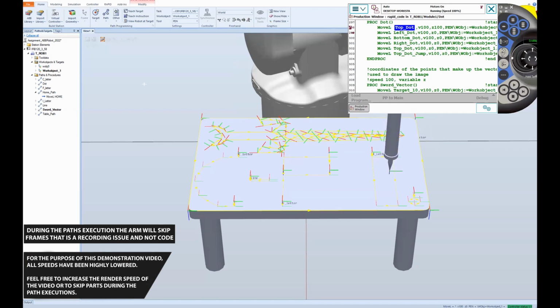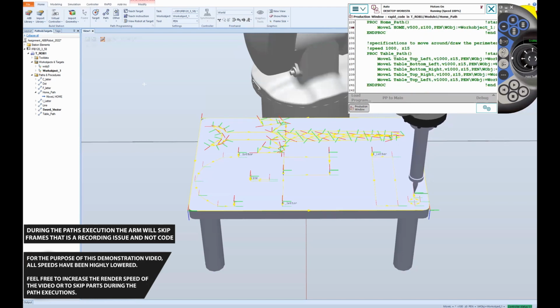So as an example, if the user is at 5 meters away from the system, the speed can be reduced to 80%. If at 3 meters, the speed can be reduced to 60%. If at 2 meters, the speed can be reduced to 40%, and at 1 meter, reduced to 20%. Anything lower than a meter, the entire system stops and exits the program. This can be extremely easily implemented, and the code does not require much modifications.